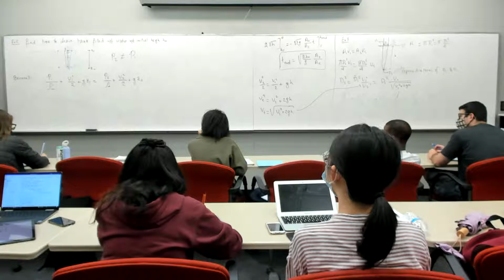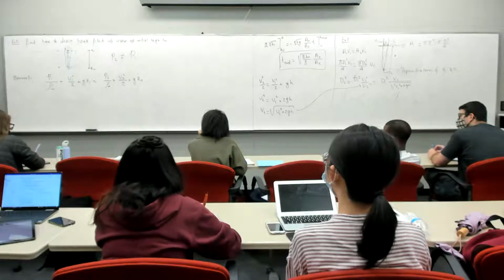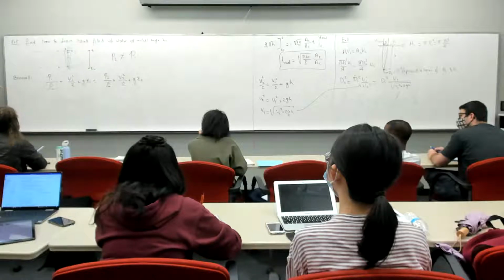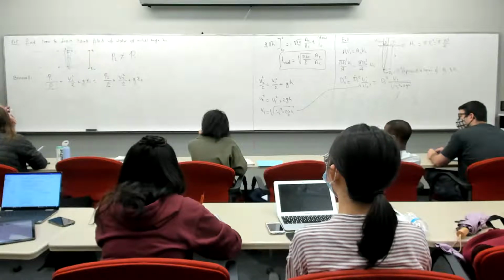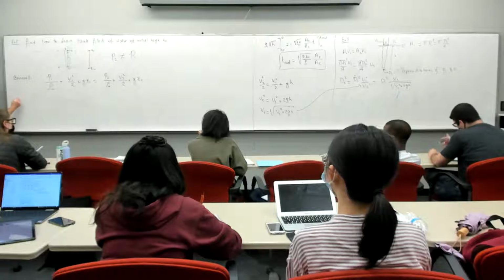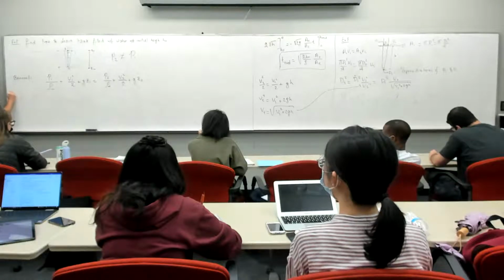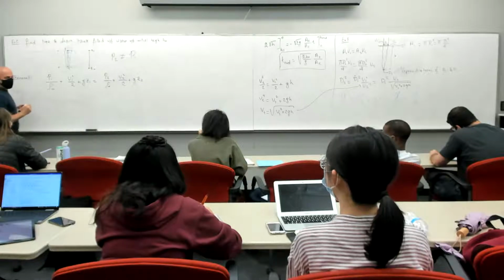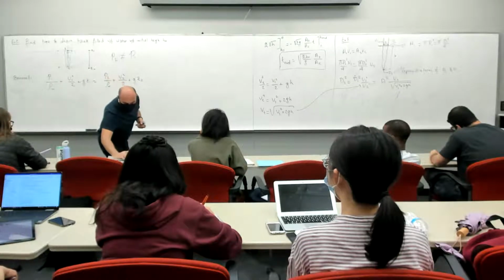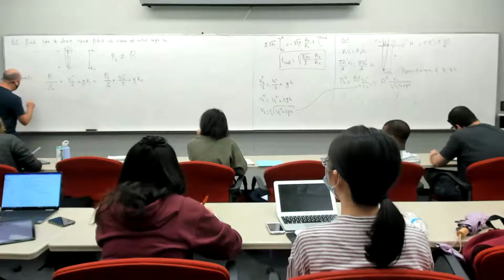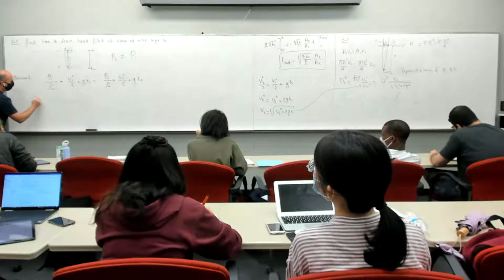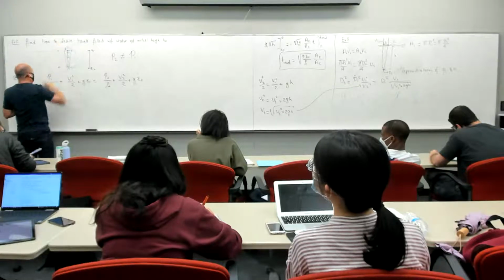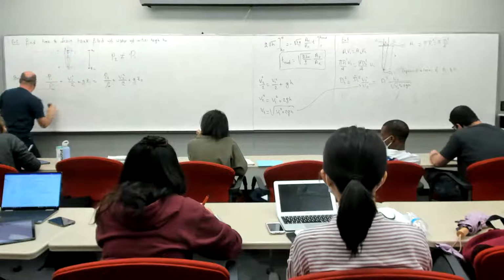So you take a point in oil, and get the pressures from the oil. And again, from statics, we know that P1 is, what's that formula? It's rho oil G times whatever H is above you. Or actually, let me do it in a better way.